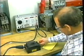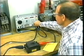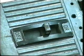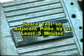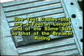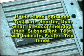The overcurrent trip test is performed on a molded case circuit breaker to verify the time current characteristics, or inverse time, of the device. To avoid false test data, you should space any repeated test on any poles by at least 20 minutes. Space test on adjacent poles by at least 5 minutes. Use test cables that are 4 feet in length and of the same size as that of the breaker rating. If the times between tests are shorter than what is recommended, then subsequent tests will indicate faster trip times.